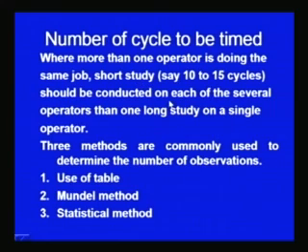And so, if the same job is being carried out by a number of workers, it is always good to carry out the time study on a number of workers instead of selecting just one worker for the study. And when a number of workers are carrying out the same job, a few cycles, say 10 to 15 cycles, can be timed for each operator for each element, so that a representative picture, representative time values for each element, can be obtained instead of going for a very long study on a single operator.